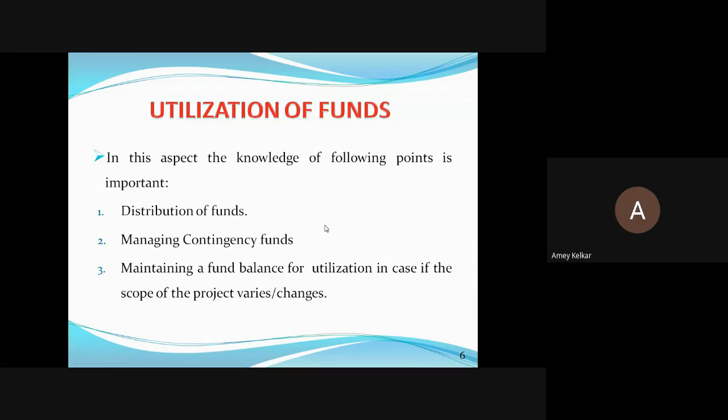So generally it happens with the vibrator needles which we use for compaction on site. The equipment gets damaged. So we cannot say that the equipment is damaged and will not do vibrating. We have to do compaction, and manual compaction will not yield that result. So that time what we have to do, either repair the material or replace or do some adjustments. Again, for such things we require some funds called as contingency funds.